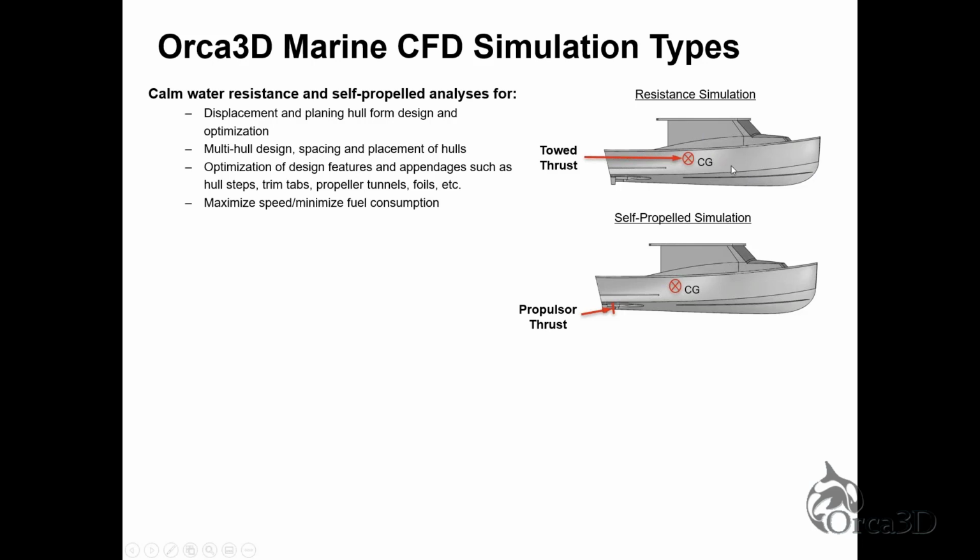So this type of simulation is very good for optimizing your design, maybe adjusting your hull form in order to figure out how to make the drag the smallest, adding lifting strakes or spray rails for a high-speed planing boat, or if you have to have a tunnel because it's a very shallow water boat, you want to determine how to design that tunnel so it has the least negative impact on the drag. You can look at different tunnel shapes, for example, and find the shape that is optimum from a drag point of view.